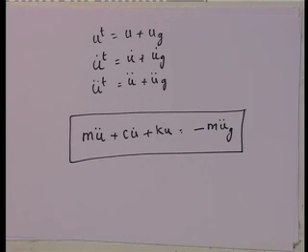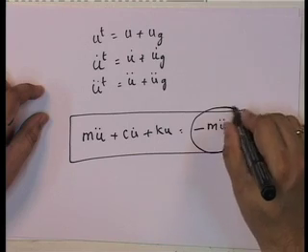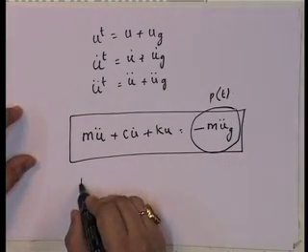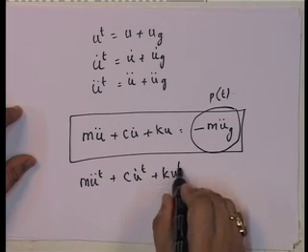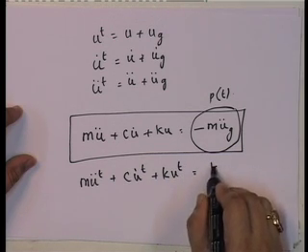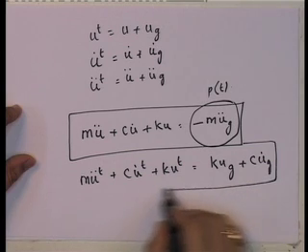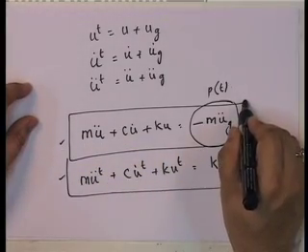Of course, the other way of looking at it, if you really look at this, basically this part is your P of t. The other way to write it, again in terms of the total, is this, the other way to write the same ground motion. This is a lateral ground motion, and therefore these are the lateral degrees of freedom. So either one of these is valid, but this is the one that we typically use.